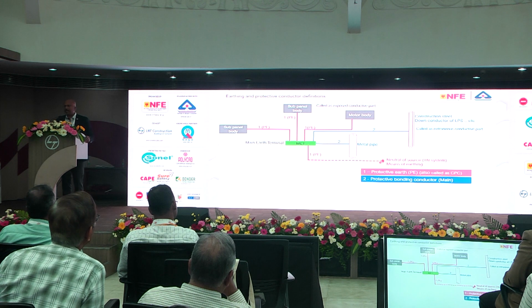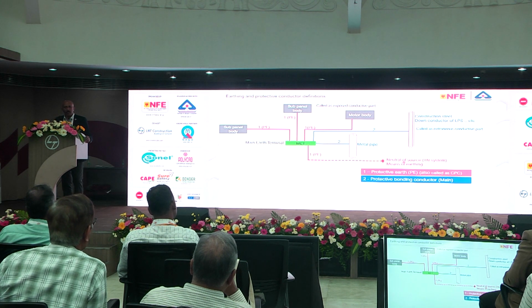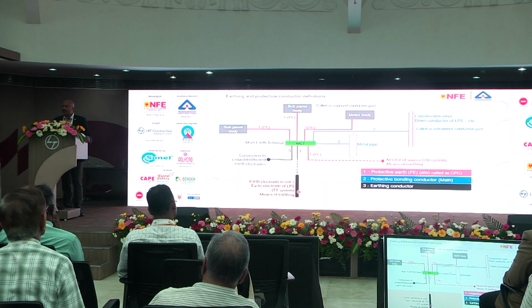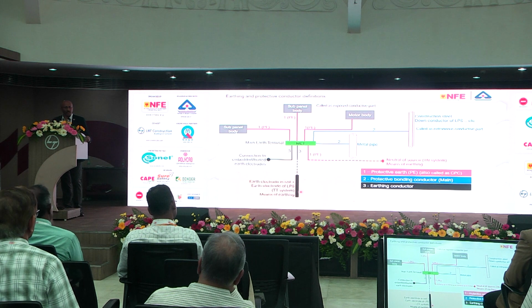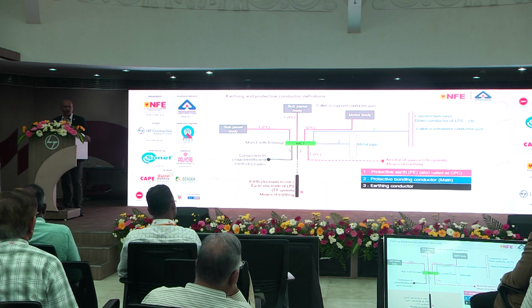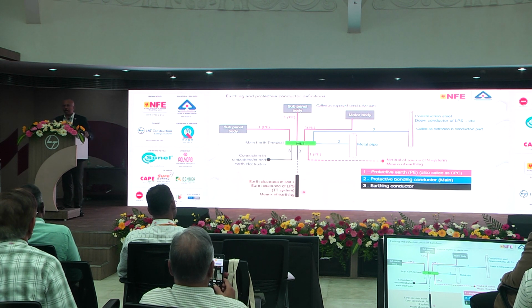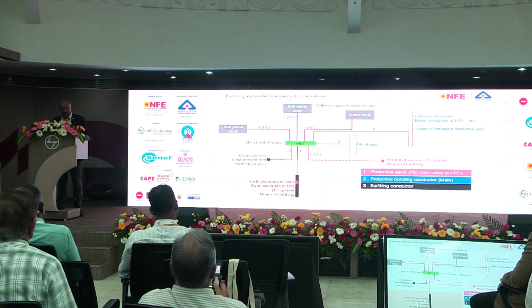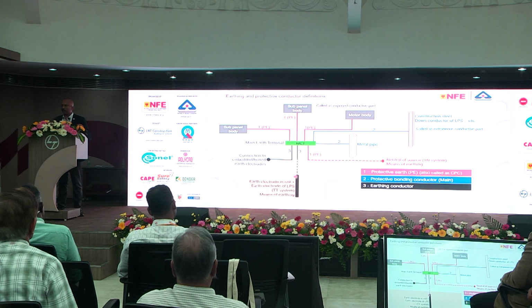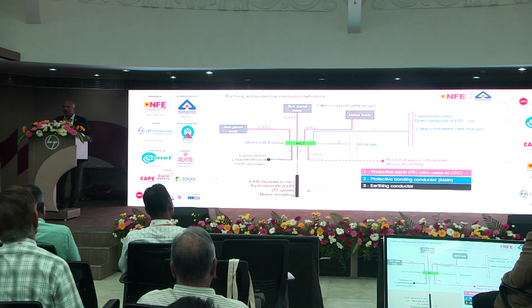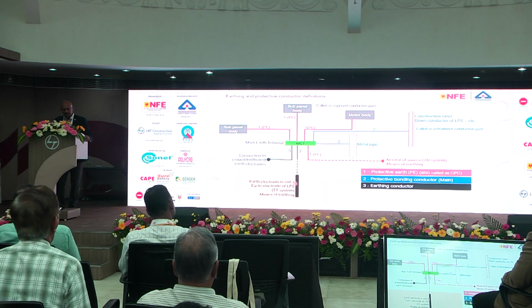Then, electrical systems are classified into TN, TT, IT; we will come to it in the afternoon. If you have a TN system, the MET is connected to the neutral of the transformer or the DG. If you have a TT system, the MET is connected to an earth electrode in soil. TT is applicable for low voltage electrical distribution sometimes. As per our regulation, we are not supposed to follow TT, but our electrical distribution companies almost every time follow TT. So there is an earth electrode in soil. Regulation 16 also says even if you have a TN system, for three-phase consumers, you make an earth electrode. So basically the MET is connected to the soil through an earth electrode in case of a TT system.